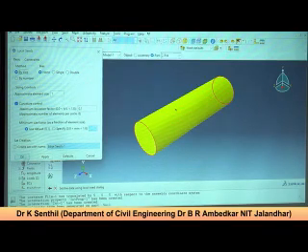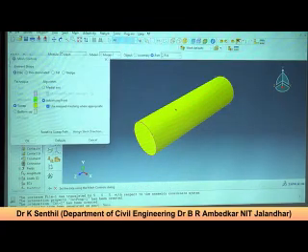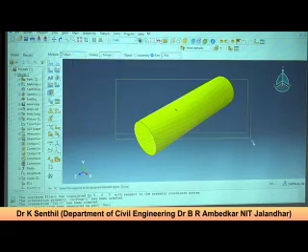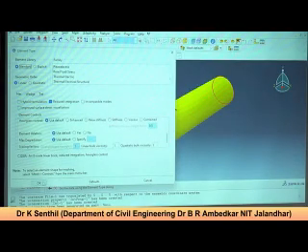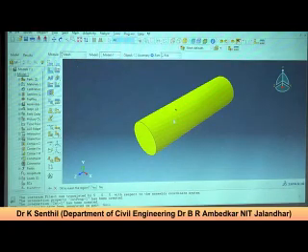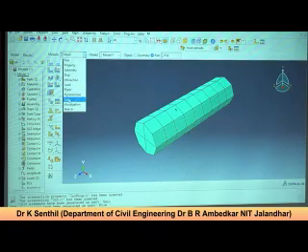So for this also I can keep the same size. That's all. Now for the controls you can use maybe hexagonal, that's fine. Element type, it's okay. The same standard analysis, and then you can change it as per your requirement. Now go to the meshing by region wise or part wise. Yes, that's it. Okay, now you can go to the optimization. Once you are familiar with this procedure or the trials, then you can do the optimization. It's not a problem.